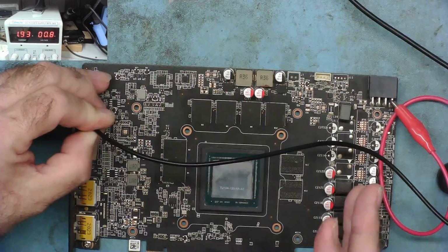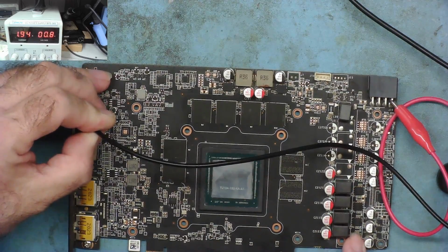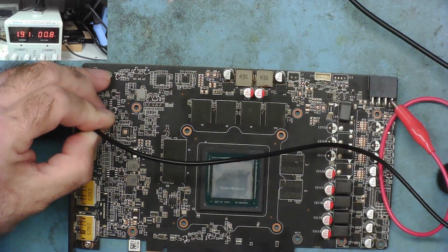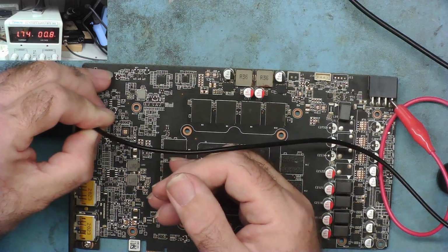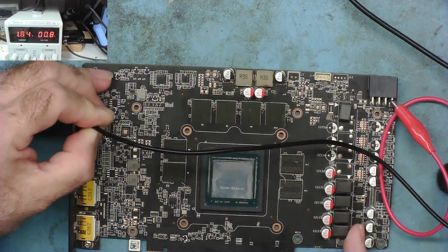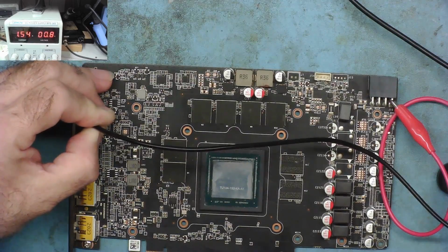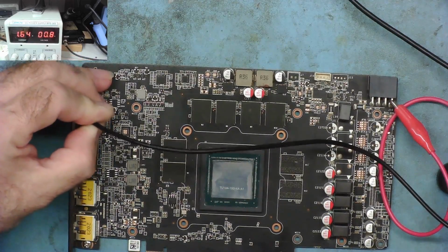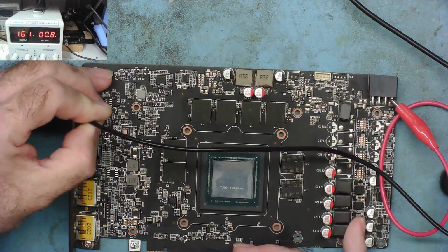Now, is the faulty part getting warm? And the answer is no, it isn't. I'll leave it on a little bit, give it a little time to see whether this actually gets warm. The GPU isn't particularly warm either. In fact, it's cold, really. Probably the reason it's wandering around slightly is a slightly bad connection on the end of the wire here. Any very slight difference in the resistance of the connection, or where I'm connecting to the ground or here, will obviously cause a slight fluctuation. Okay, it's been on a little while. No, it's not getting warm.